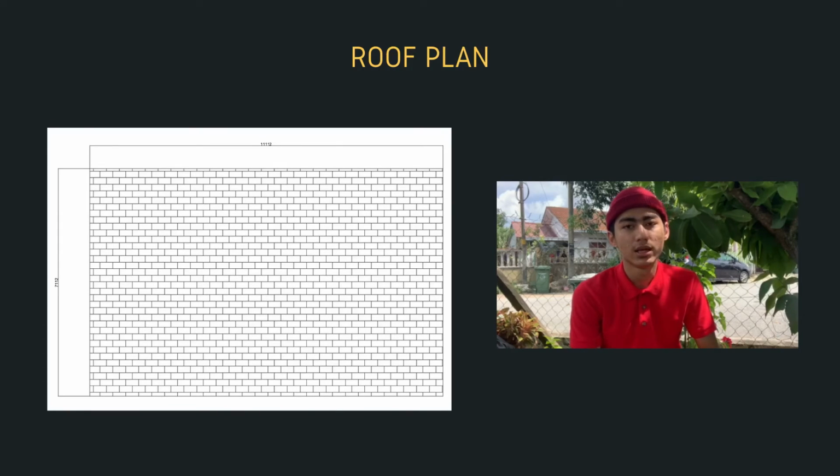Next is the elevation. An elevation drawing is essentially an orthographic projection sketch that depicts one side of a house. As a result, there are four elevations: front, rear, right and left. An elevation drawing's goal is to represent the finished appearance of a specific side of a building and to provide vertical height dimensions. It's a standard drawing with one on either side of the structure.